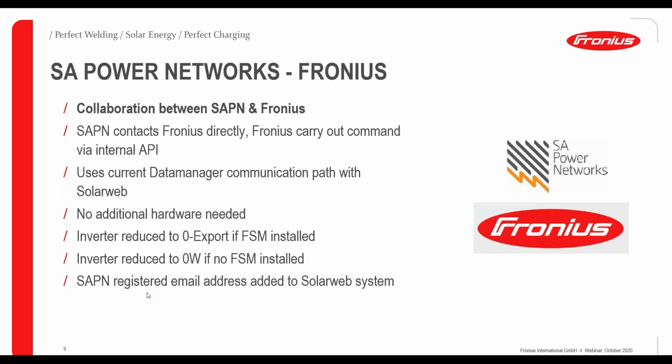So this is the one we briefly mentioned last week. This is SAPN Networks as the relevant agent, with Fronius doing the actual control of the inverters internally. That's a collaboration between SAPN and Fronius directly. In that case, SAPN contacts Fronius directly, via a phone call as they do it, and we carry out the control via the internal API. It does use the current data manager communication path to SolWeb.